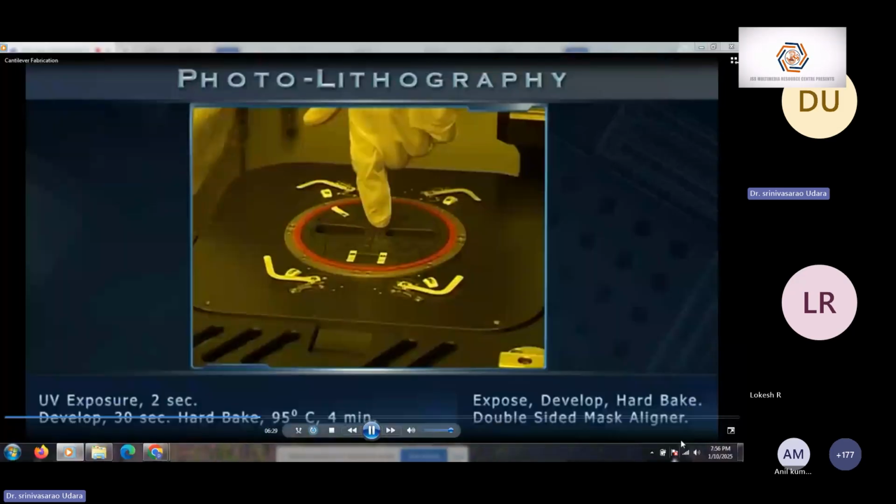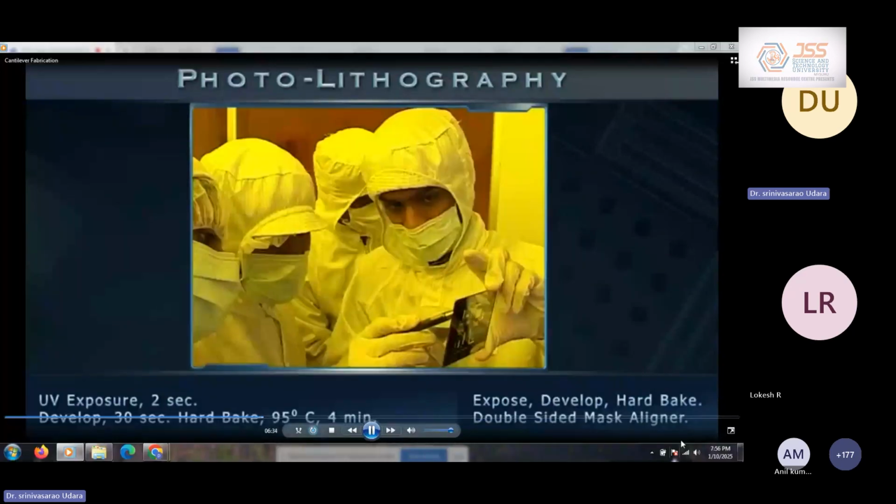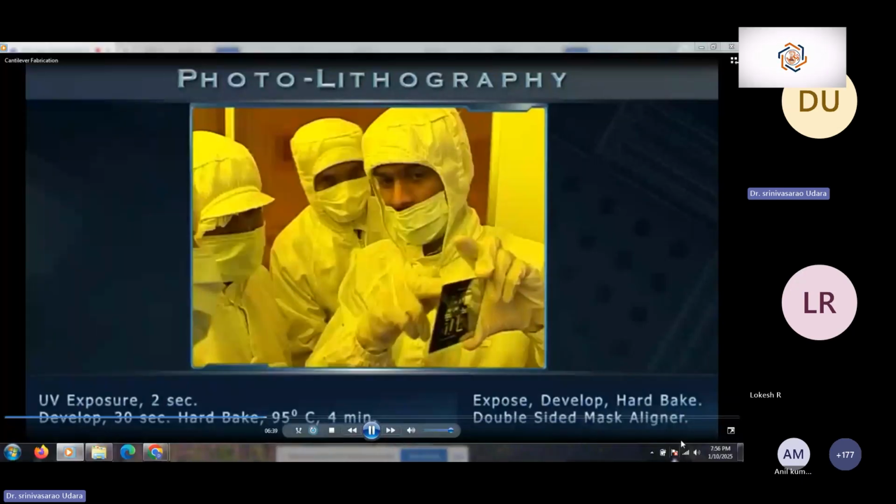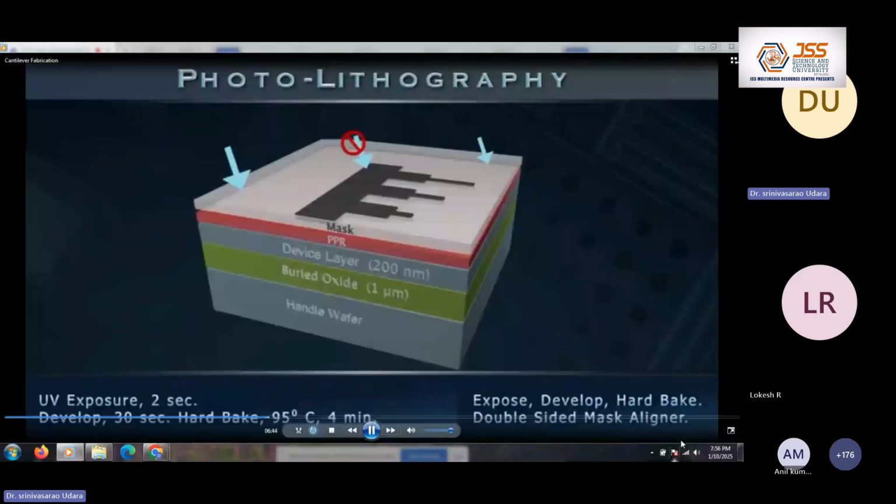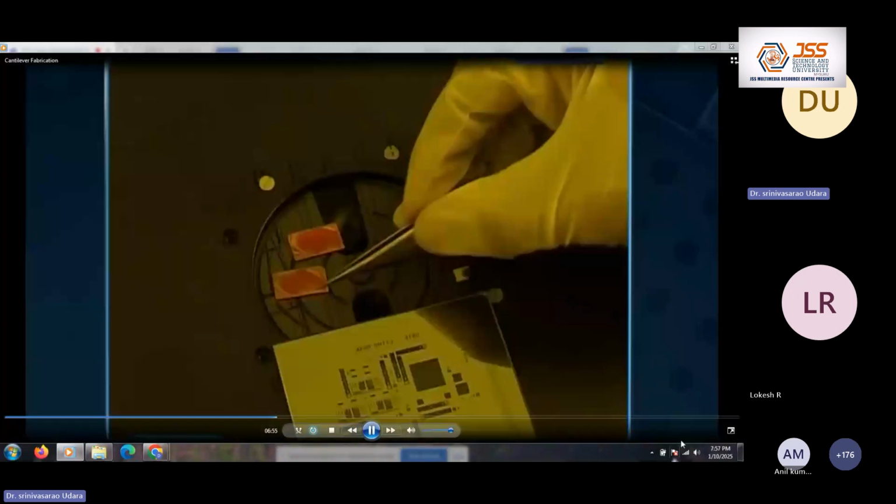First, we pick a cantilever mask prefabricated especially for INUP from our mask library. The mask consists of transparent and opaque parts that define a desired pattern. When we place this mask over the resist-coated sample and expose to UV light, cross-linked bonds in the resist are broken. We first load the samples onto the mask aligner tray.